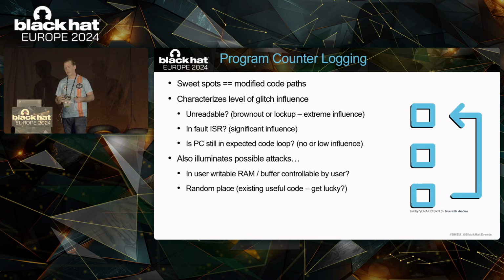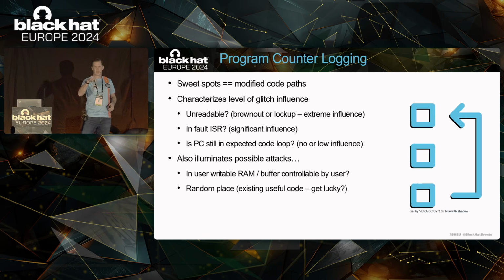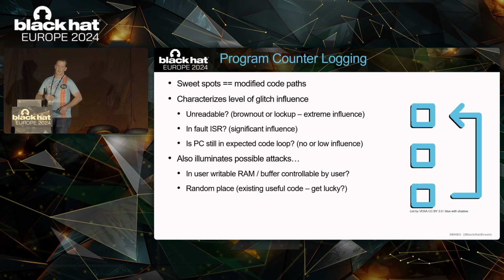That's more of a medium level influence. Or maybe the PC is still in the expected code loop. In our case, we were attacking the bootloader, so it was in a serial receive loop. If it's still in that loop, maybe it only jumped one or two instructions, or maybe it jumped no instructions. So that's kind of a low or an optimum influence in some ways.